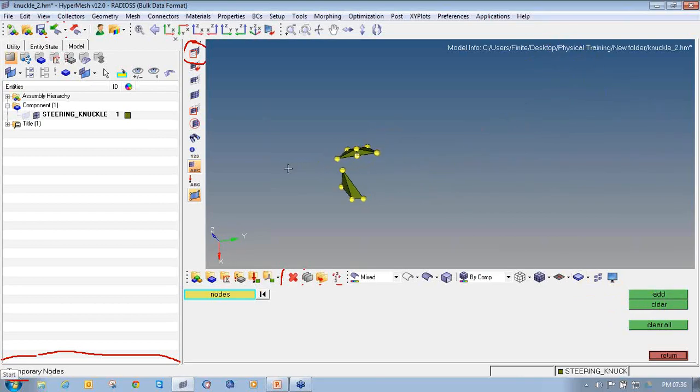As I already told you, TET collapse is the height of the tetra element. So as you can see for this particular element, the height is very less as compared to its base and hypotenuse. So either you can decrease the hypotenuse length or increase its height. It will improve the TET collapse.